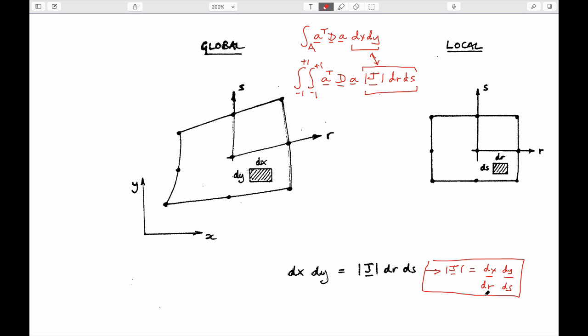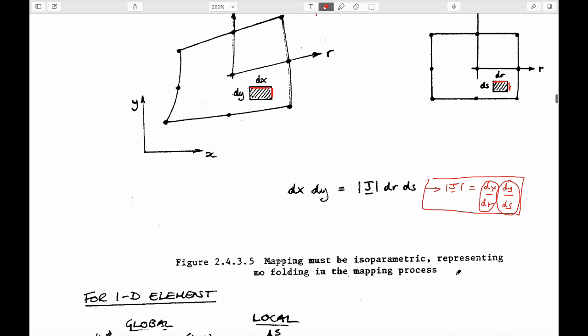And so if you look at these individual terms, dx over dr is just however big this length was here in this image to however big it is in this image. And the ratio of those two lengths is this number. And likewise, the length of the same patch in each of these cases, in each direction, both the global system and the local system here is this here. And if we know what those numbers are, then we get a scaling value that just maps one to the other. So it allows us to map from one system to another, nothing more than that.